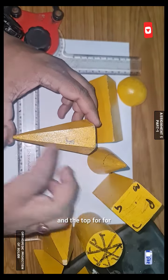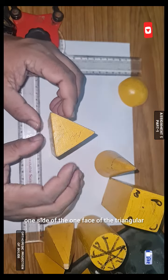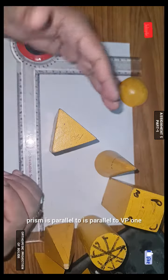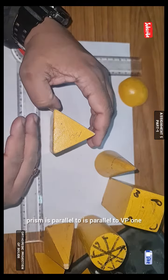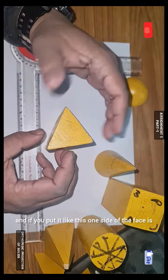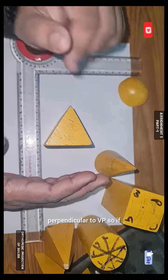In the case of a prism, we can put the object like this, and in this position it is called resting on its base, and one face of the triangular prism is parallel to VP. If you put it like this, one face is perpendicular to VP.